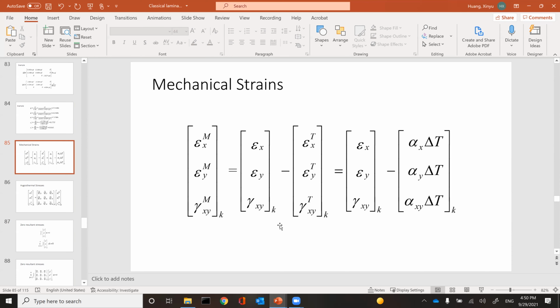There usually is something called a zero stress temperature, which is close to the curing temperature. So when you cure the matrix, with all the layers together in the autoclave, that's when there's absolutely no stress between all layers. Once it starts to polymerize and form each layer, they start to build stress.